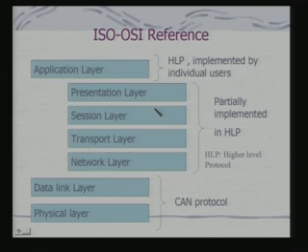And they need not implement all these layers; they would implement some of the functionalities that are required for them. Now, this model is very important for you to understand when you are talking about networking embedded systems. You really do not always need the full-fledged functionality of all OSI layers. Wherever the functionality is needed, you need to exploit it. These functionalities may be application specific and some part of the functionality can be standards based. So, for CAN, data link and physical layer are the specification of the standards, and the remaining can be purely application based.